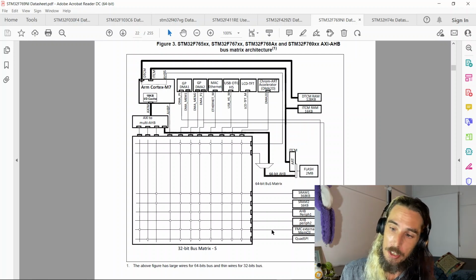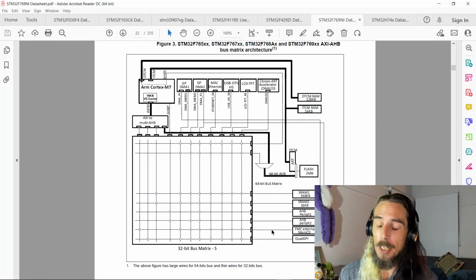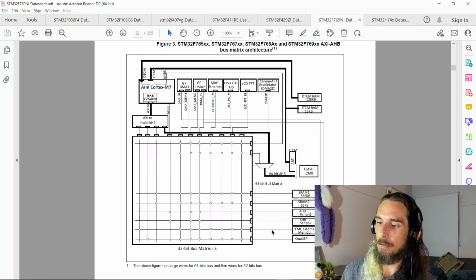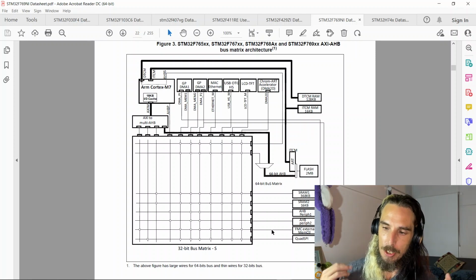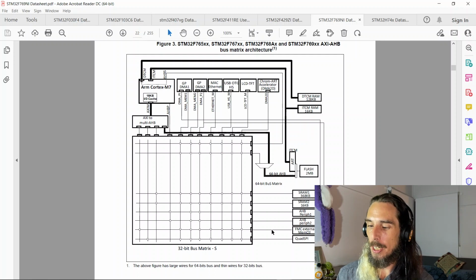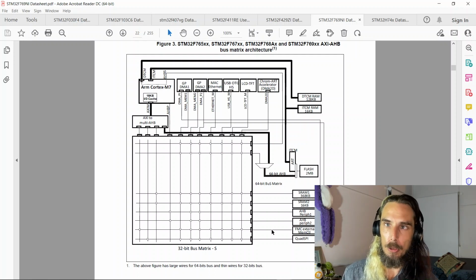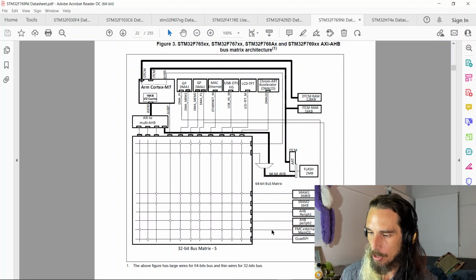And it's not because the CPU itself is being overloaded, it's because you're starting to overload buses. That's something that I have actually come across before, and using the diagrams and having an understanding of how the various buses and the matrices and various components connect together, you can try and find workarounds and leverage more performance in order to avoid those sort of situations.